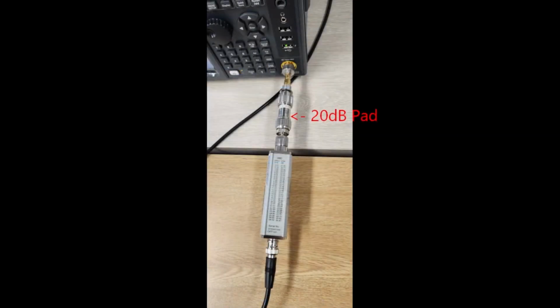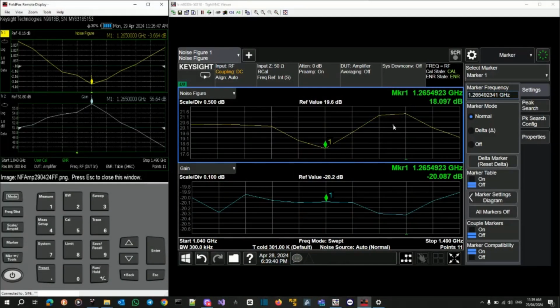This is how it looks for the connections. I have the noise source connected directly to the spectrum analyzer through an attenuator. If you remember, the reading on the FieldFox for this attenuator is roughly about 19.6 and the loss is about 19.8. So it's very similar. Something changed here, could be the matching to that port because I do have an extra adapter on that.